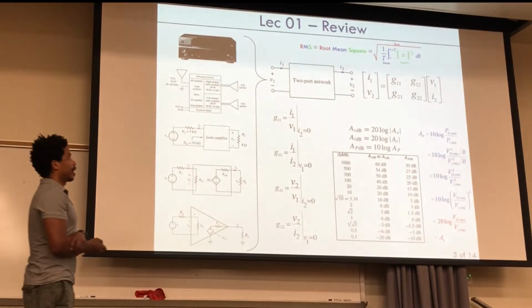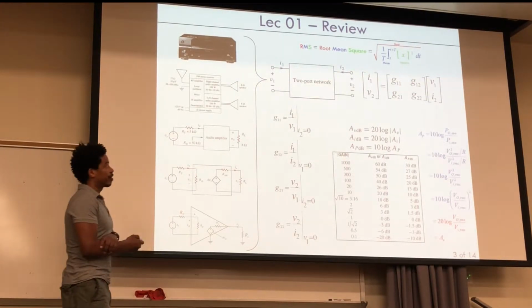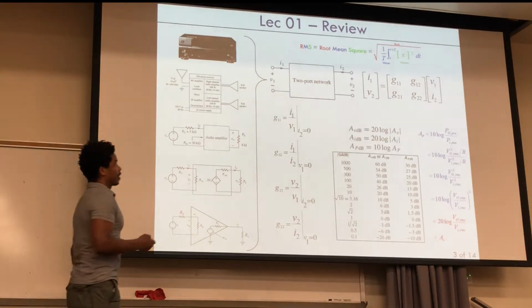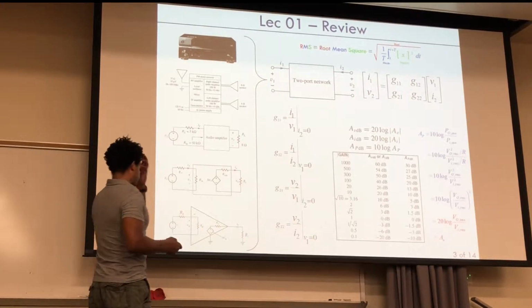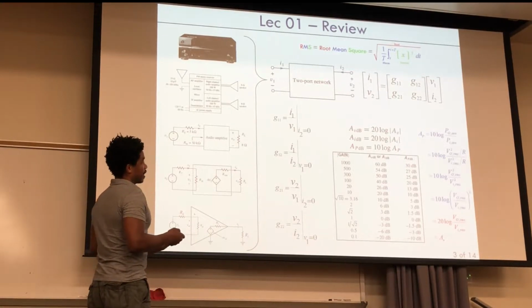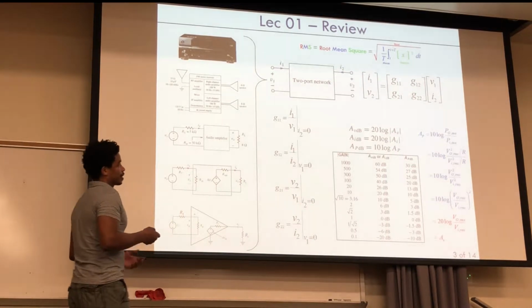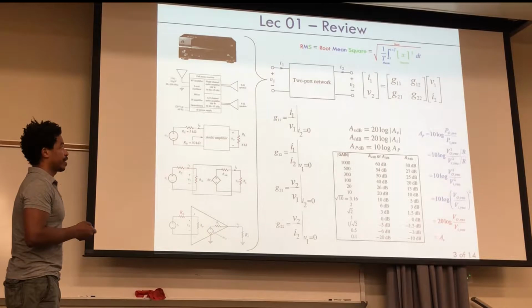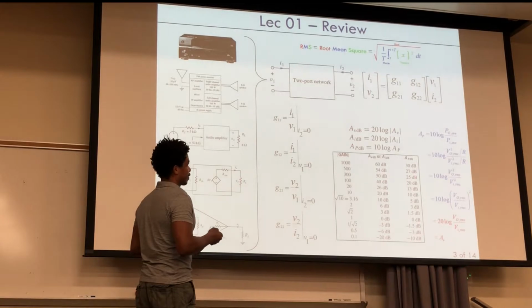We also looked at decibels. Okay, so if it's power, you have this 10 log of the ratio of output to input. If it's voltage or current, it's 20 log. And then we saw that with these things, they really mean the same thing, right? It's just that when you write it out, they look different because you have to say this right here is the gain in terms of power. Here's the gain in terms of voltage or current. So you have to say which one. Once you say which one, then these make sense, right?